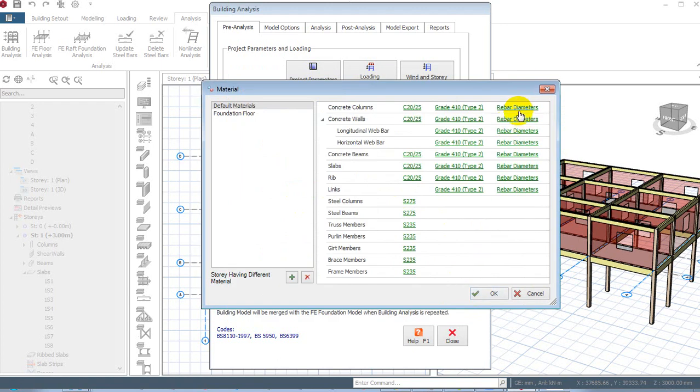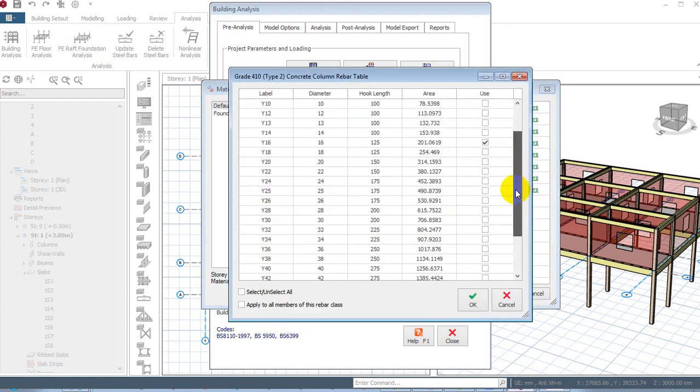You are at liberty to choose as many sizes of reinforcement, but most times it has to do with the number of stories, from your experience. If you are going up to 3 floors, maybe having two suspended floors, you may most likely have a Y20 on your ground floor. But what we are designing now is just one suspended floor. So Y16 on the ground and Y16 on the first floor, I think it's actually going to be okay.